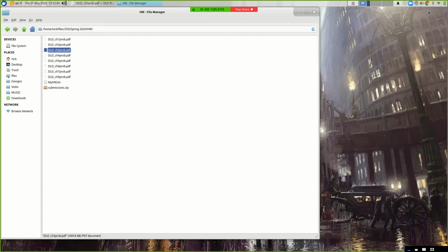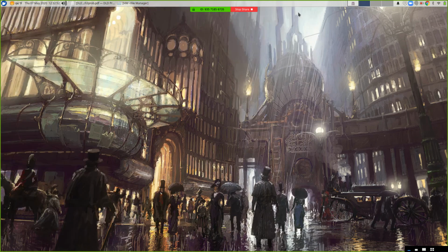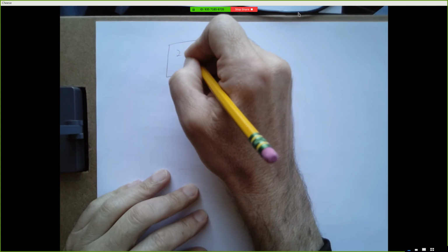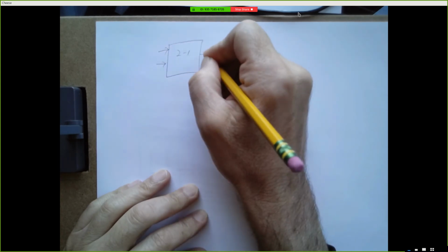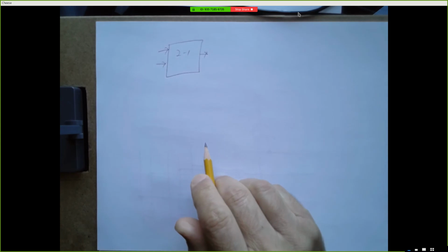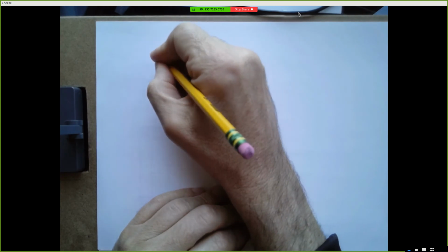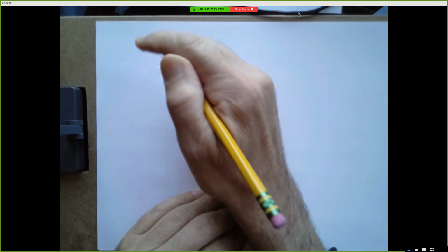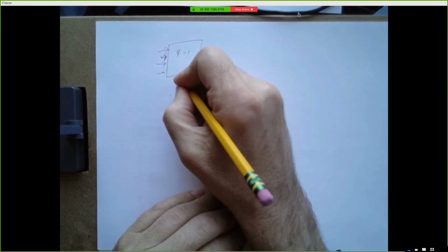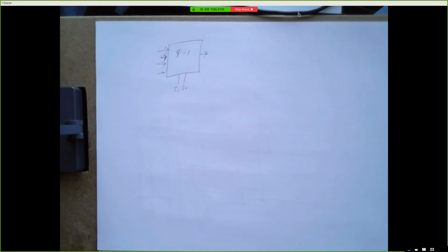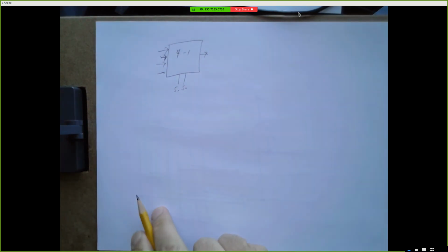All right, so let's talk about Muxes and DeMuxes and encoders and decoders. So remember our basic setup, right? A mux was something that took multiple inputs and turned it into fewer inputs. So with 2 inputs, we can choose one to generate an output from. A 4-to-1 would have 4 inputs, and we can choose which one to send to the output. And you have a series of select bits, and depending on how many inputs you have to choose from, you might have 1, 2, or more select bits. So for 4 inputs, we need to choose one of 4 things, we need 2 select bits.